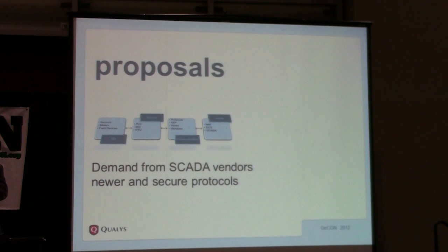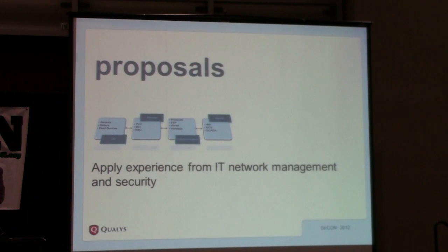In more than one instance, we have seen a check mark saying, oh, we have secure DNP3, we have secured this, we have secured that. But when you do an assessment, the old protocols are still being used. So, okay, you bought the new software, but it was never really configured to make use of these new security features. So make sure that's done.